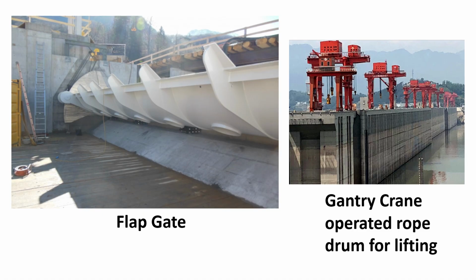Here, we can see flap gates. These are generally for low head and low discharges. They will move in the direction of water to pass the flow. Gates are generally heavy weight equipment. Lifting components shall also be heavy and withstand these loads. Gantry cranes serves this purpose. These gantries are used for moving purpose to operate gates at different spillway or fixed type.